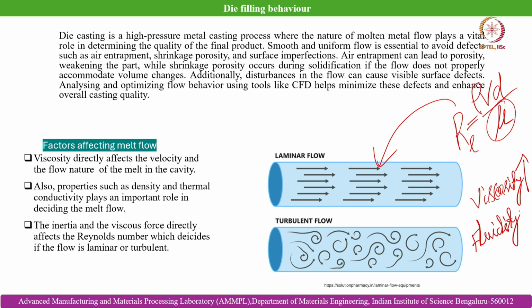But there should be a trade off, because slightly lesser fluidity is in demand in cases with non-ferrous light metals like aluminum and magnesium, where significantly higher melt velocity and lesser viscosity can cause several defects, starting from gas absorption to dross and several others.